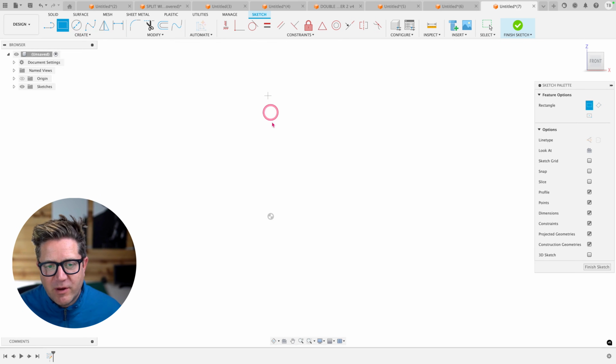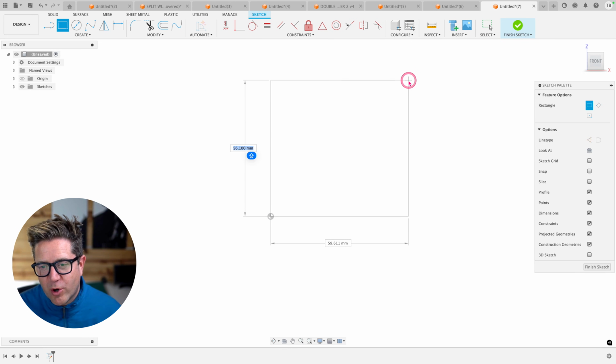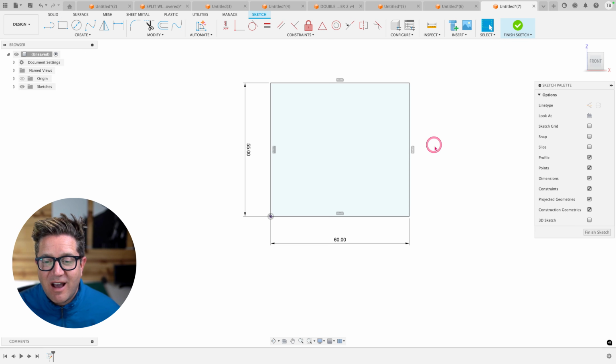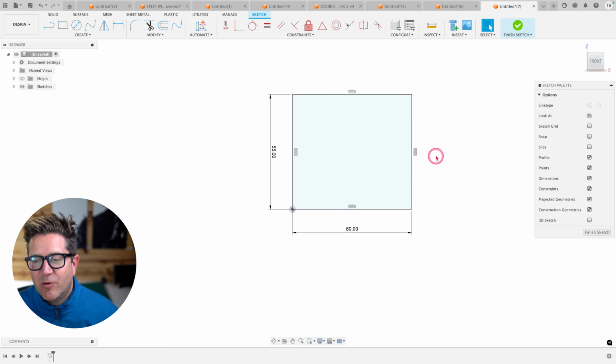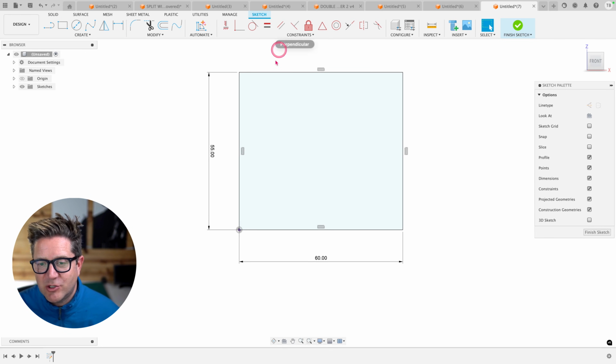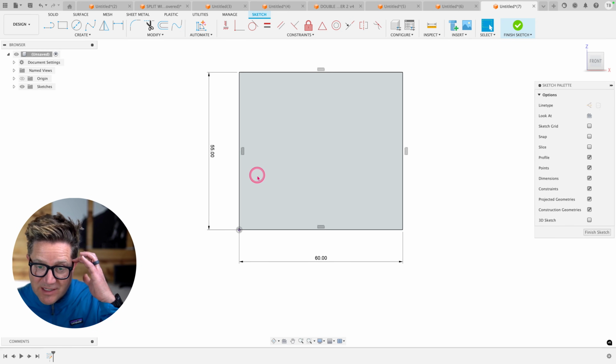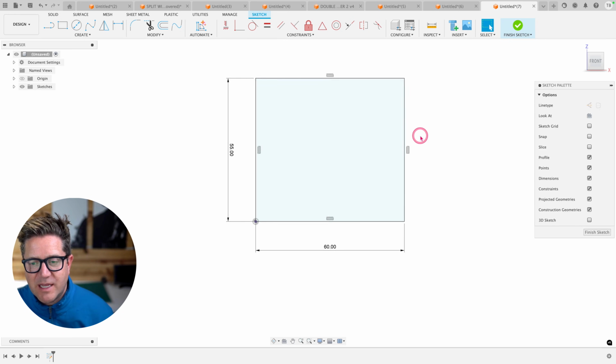I'm going to do the 2-point first. This is corner to corner so that you can align to other points, 2 points in space. But as I'm placing this, notice the dimensions. If I type in a number and hit tab on the keyboard, I now can place 2 dimensions. I have a fully defined finished sketch ready to go. So rectangles will save you time with constraints. Don't manually draw these lines if you know you want a rectangle.